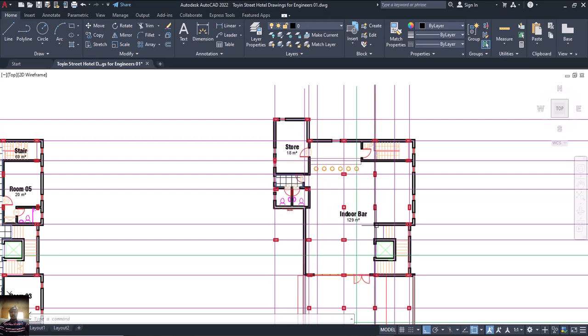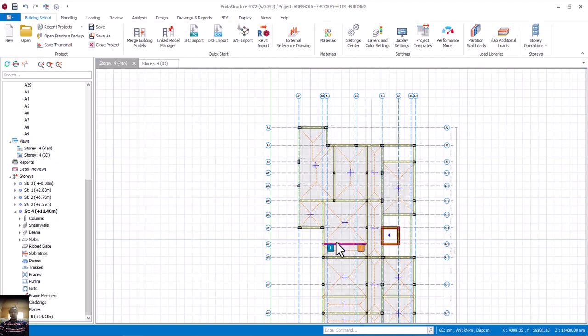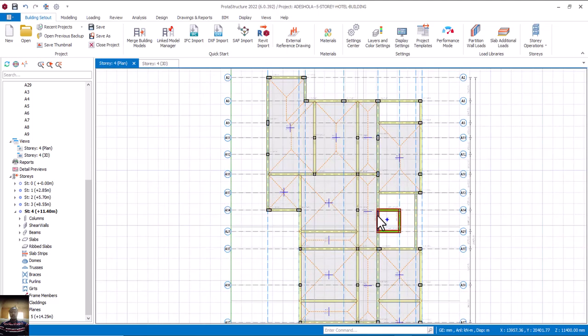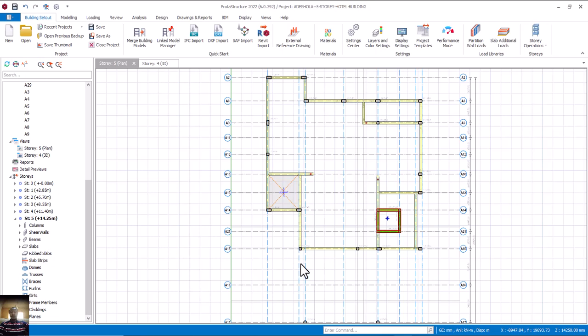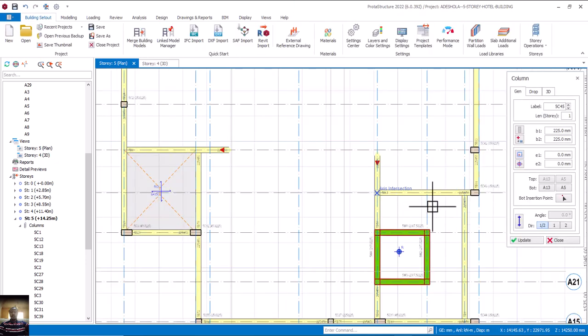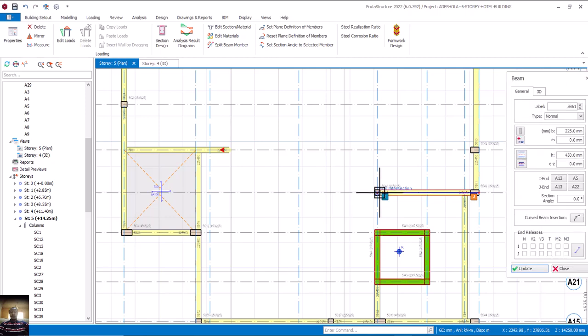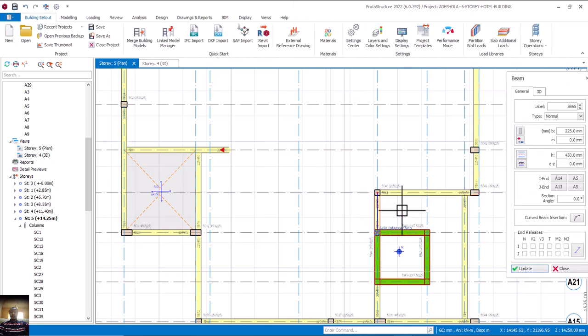Now, if you look at this place here, let's see what is happening. Let me go to Storey 4. Okay, which means I can put a column here. I'll remove this column and put a column here. That is fine. So let me go to Storey 5, then look for a column. Let me choose this one again and bring it on this. Then escape, click on this one, delete it. Then take the property of this one and insert it, and come and rest on this. So that is fine.